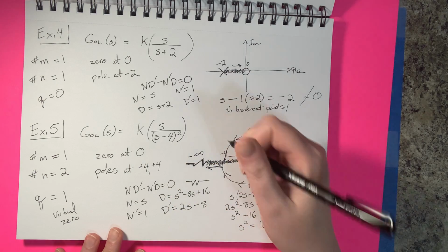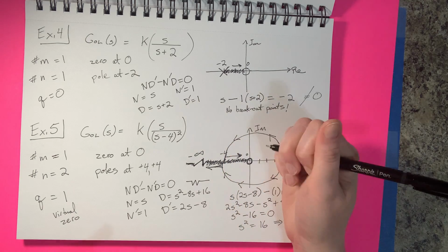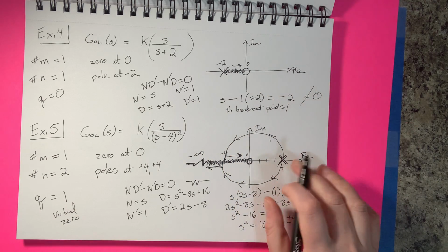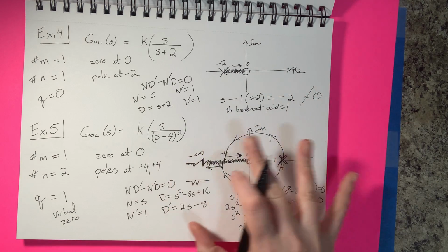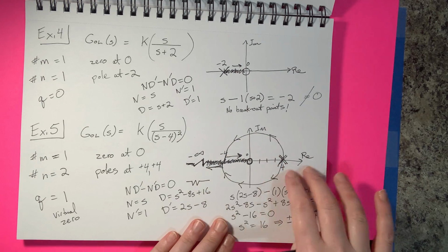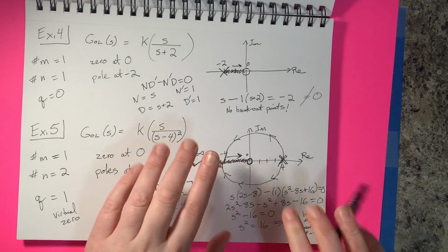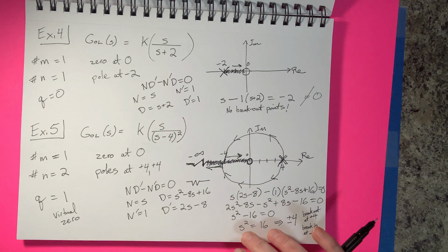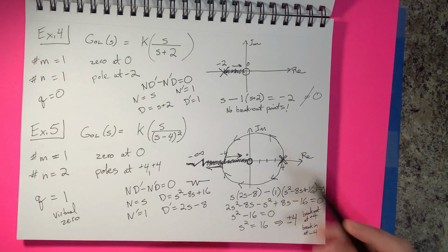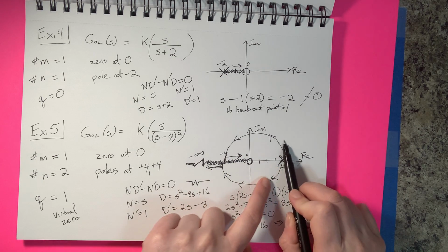I'm not so much concerned about you knowing that level of preciseness as much as the shape and drawing conclusions from the plot. Okay, so this is the correct shape. We do have the breakout, break-in points marked, and so this would be sufficient for an answer in this case. We have marked all the poles, all the zeros. We have the direction labeled.